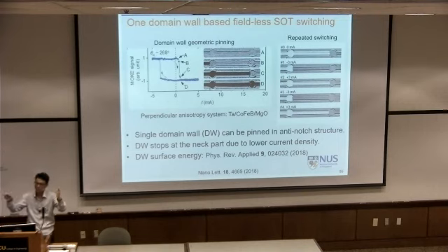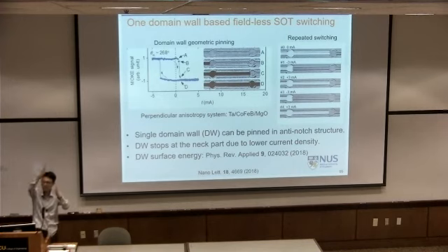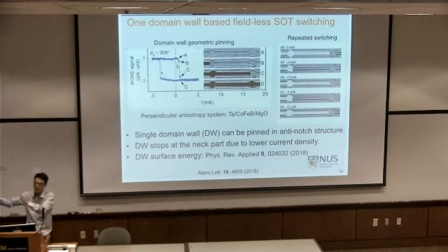If you now reduce your pulse width, the required current increases, and then increases crazily. So basically this quasi-DC regime is the thermally induced switching regime. And if you shorten your pulse width, you can go to a more pure dynamics regime coming from your magnetic